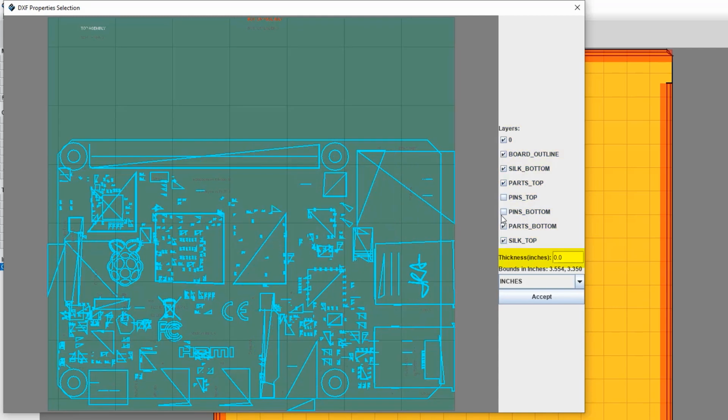Step 2, thickness. Protocase Designer cannot automatically detect what thickness you require, so you can use this tool to set your thickness. Two important things to note: the thickness value is in inches, and your thickness choice will not be visible until the component is displayed in Protocase Designer's 3D editor window.